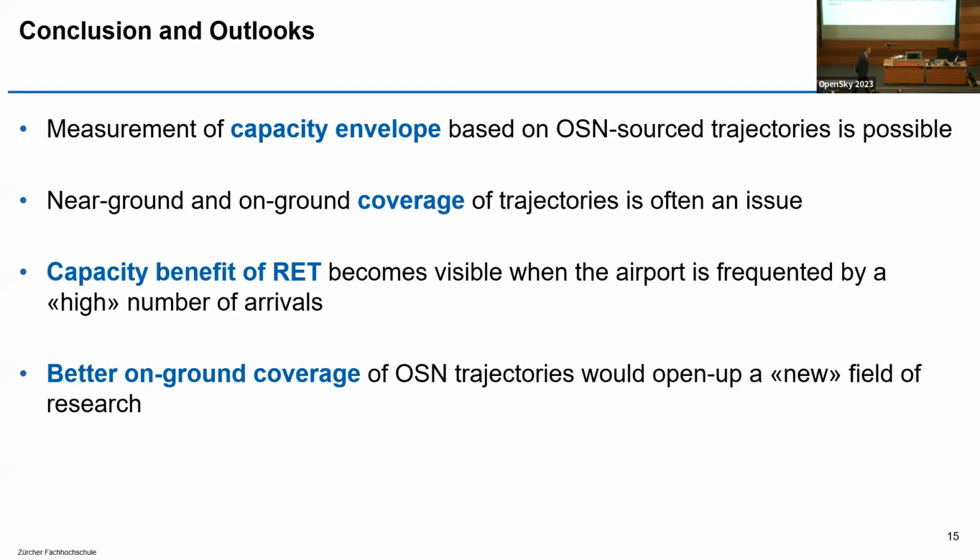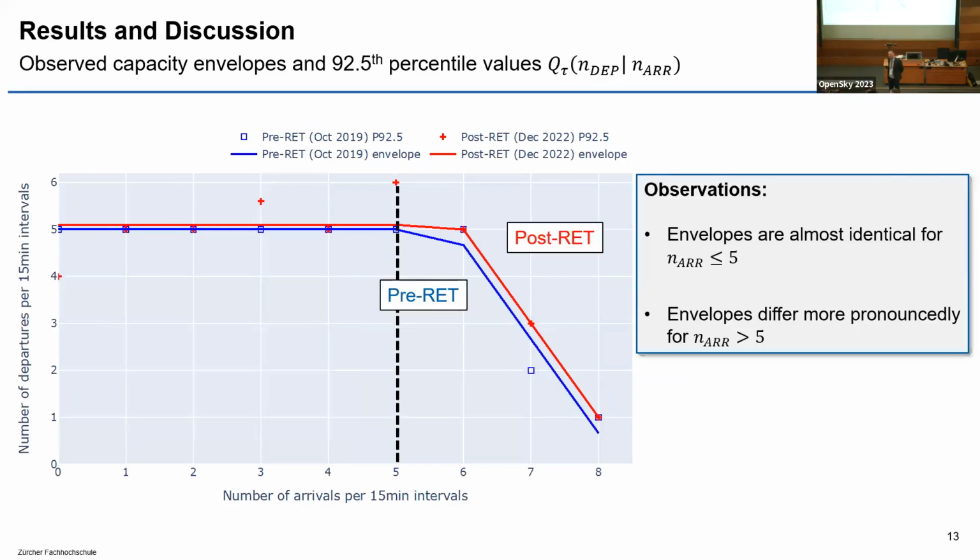Perfect. I have a fundamental doubt on what you have presented, because this kind of curve presenting capacity based on what is happening means that the airport is at its maximum level, something that is not always true, depending on the fleet mixture and things like that. We used to do this kind of thing based on runway occupancy time measures, a long time ago with a clock. Right now, not with a clock, but using data for surface movement or from ADS-B or things like that. But when looking for the real capacity of the airport, this is not really capacity. This is flow of the airport. This is the aircraft flow, not really capacity.